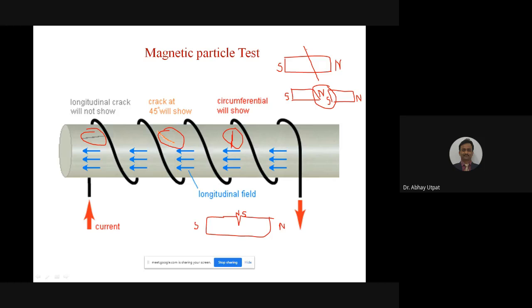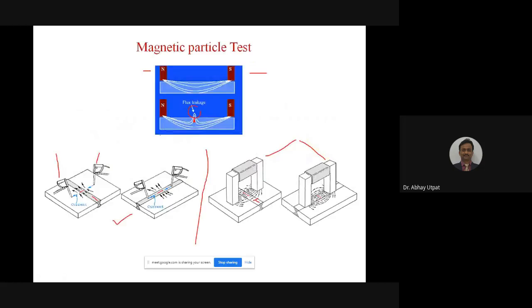Even if it is below the surface level, some powder will be accumulated. Even if you take a lens below that powder accumulated area, you will not find the crack. It means that crack is below that surface, but the limitation is that the magnetic field penetrates the part only up to 6 mm. Below 6 mm you can't check the parts. The parts which you can't magnetize or can't check with the help of magnetic particle test are then tested with the help of dye penetrant test.